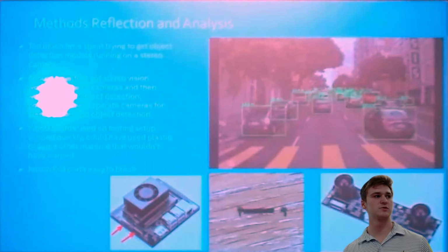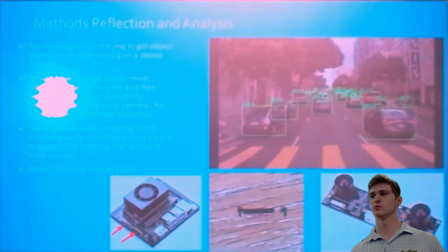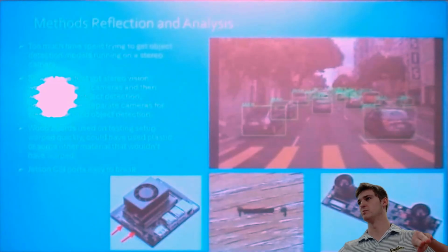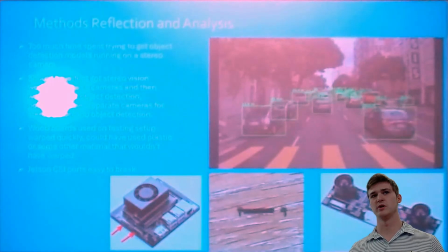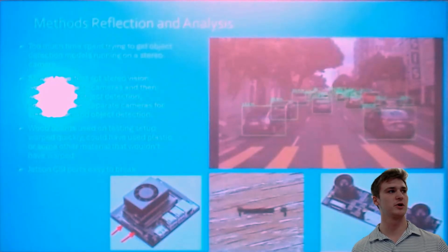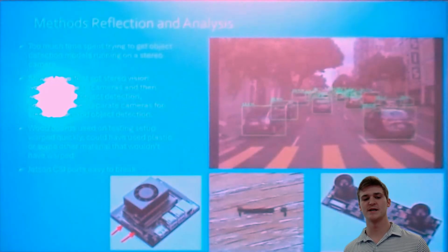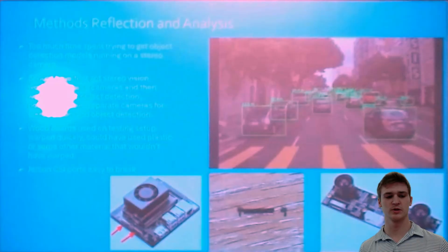The wood boards used on my testing setup actually warped really quickly, in like a week, so they completely bent. It could be from just the pressure of the screws pulling with the bearings and the lazy Susan bearing between them. But I could have used plastic or some other material that wouldn't have warped as quickly.